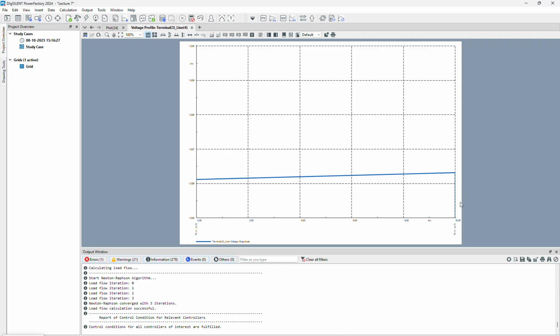If we have no loading, we normally have the Ferranti effect, and the voltage at the end of the line will increase. And when we have the load equal to the surge impedance, it will be constant. And by increasing the load, this will come down and down.